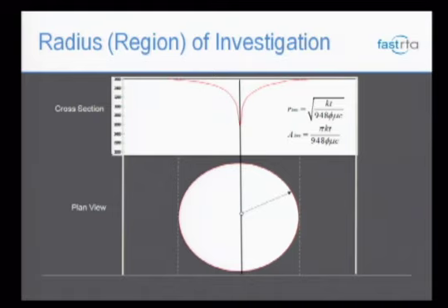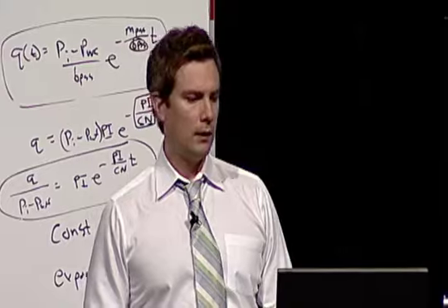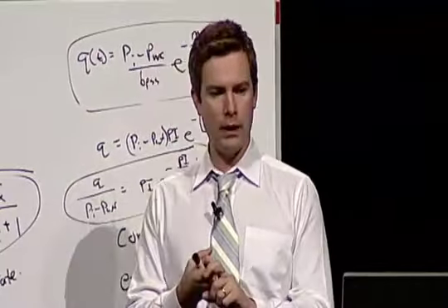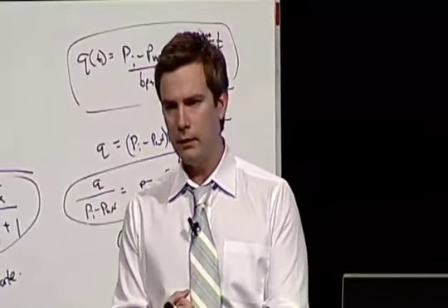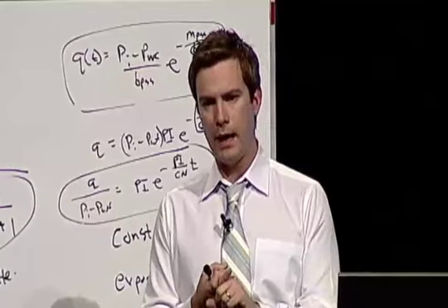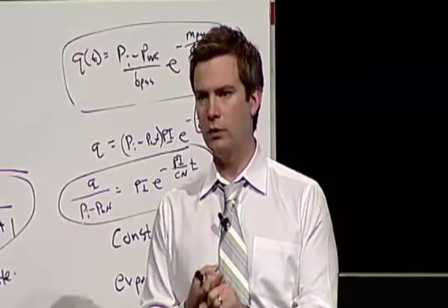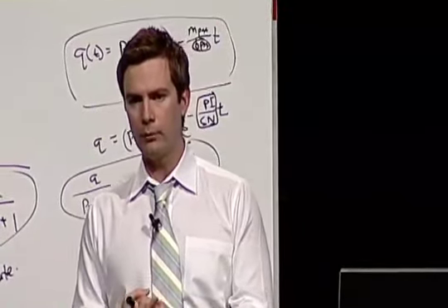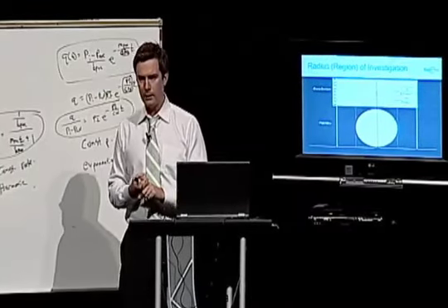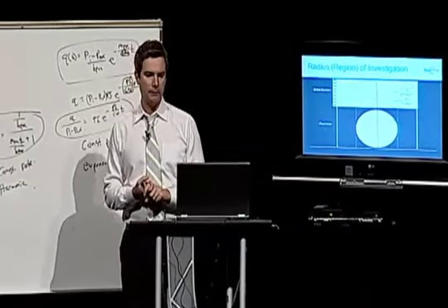And we may want to capture how far that is. One of the reasons you may want to know that is because I've been producing my well, and I know the permeability, and I want to see what my drainage area is going to be. Or I want to be able to predict how long it's going to take to reach a certain drainage area. Those are important practical questions to answer. So the radius of investigation concept will help us get a handle on that.